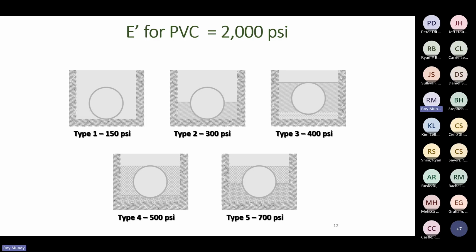They came up with the concept that when a pipe goes in a trench and you have backfill on the pipe, which is a load, and then you may even have vehicular loading going across the trench, which creates an additional load, maybe even an impact load, then that load is transferred to the pipe itself.